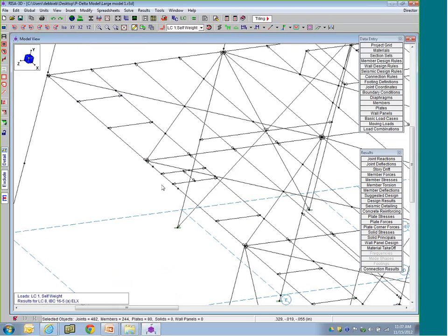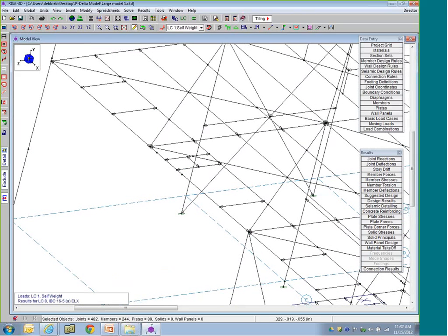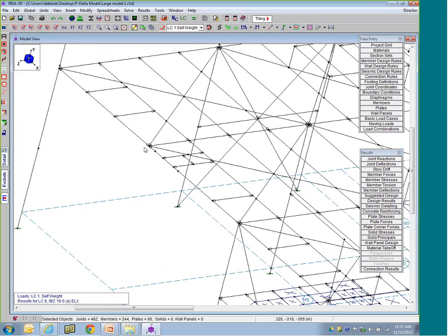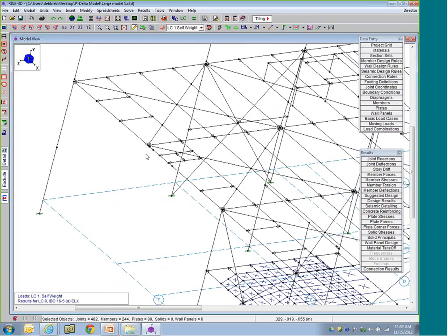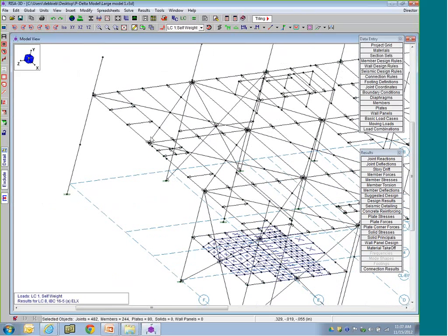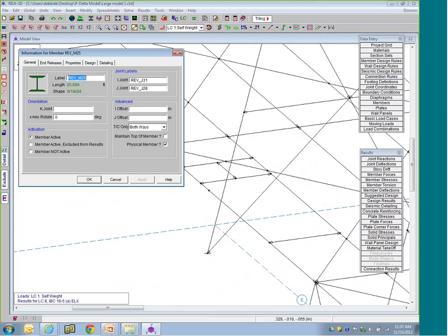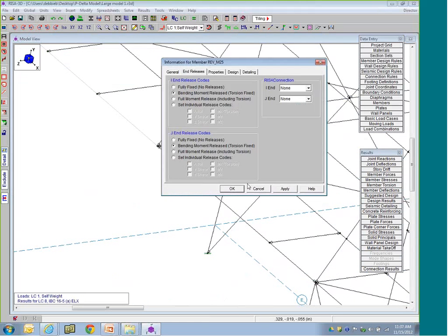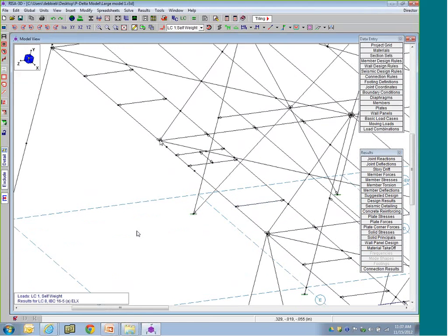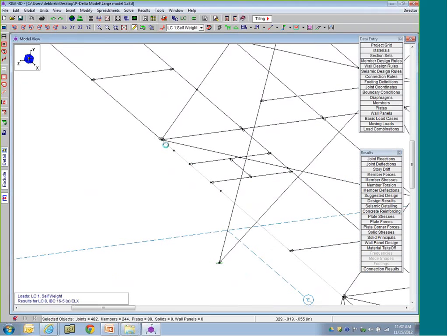But what happens is, along the whole model there's enough to hold this together that it does not become an unstable joint. So we can get past a couple of load combinations, and then it becomes just an unstable joint and P-Delta is applied to it. To fix that, you can give yourself some stability. Probably there was a column here, or maybe there was just some modeling, and we forgot to make this fixed to fixed, so that it's a continuous beam there.